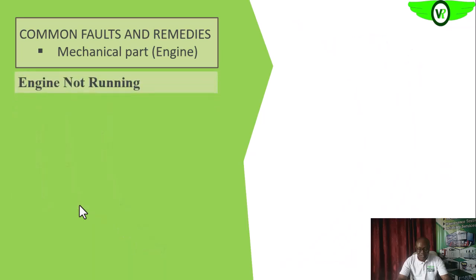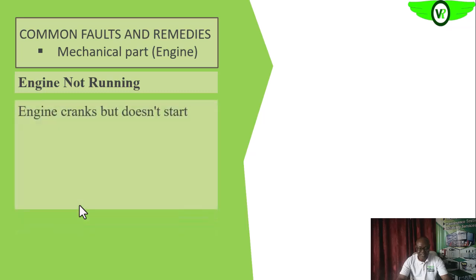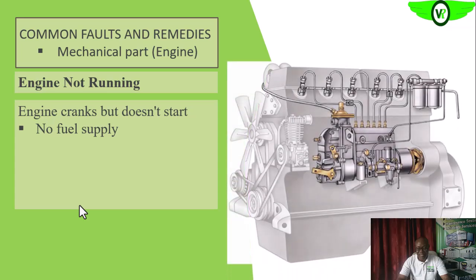So now the engine is turning and it's not starting. It's not running; the ignition process is not continuing so that the engine will continue to run. So it cranks but it does not start. It could be that we have a problem with our fuel supply.